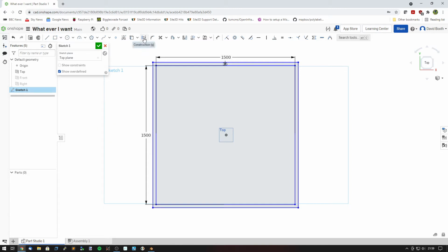But now I want to be in a construction line and I want to do an offset. So you can have those two together, and I could select one line, I could select multiple lines. I basically just want to have an offset of this line here in the other direction. So I'll click that once and it'll go the other way. And it is 550mm offset from that line. So if I left click once now, it'll take that thinking I want just 5mm, but I want 550mm. And it'll put that line there.